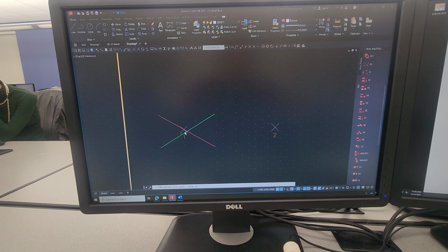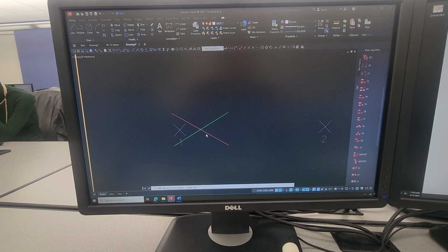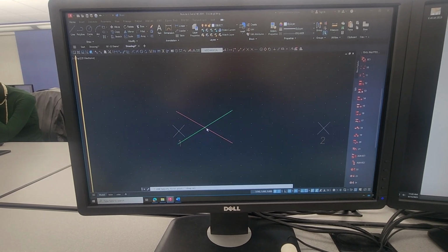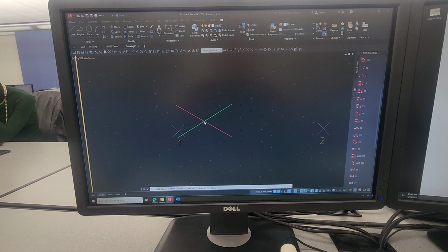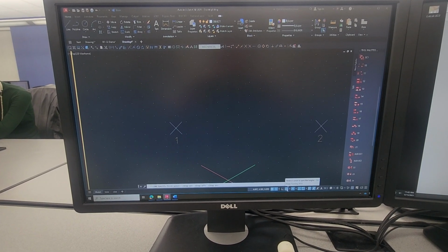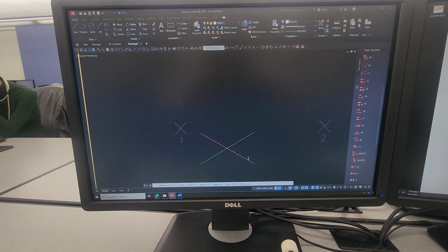F9 is what we call our snap. Some of you have accidentally hit that in the past. You say, oh my God, why is my cursor jumping around? Well, now you know. So the F9, on and off, it's off now, now it's on. It's this guy right down here. That is our snap button, cursor restrictions. So I can click it there, or I can hit F9.